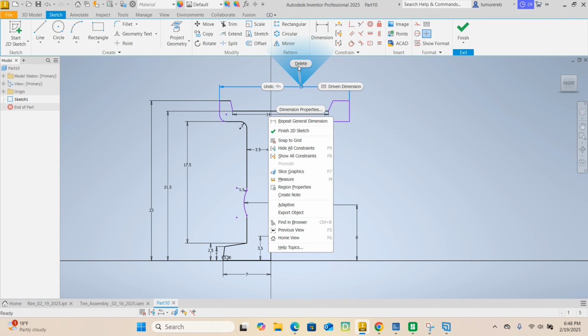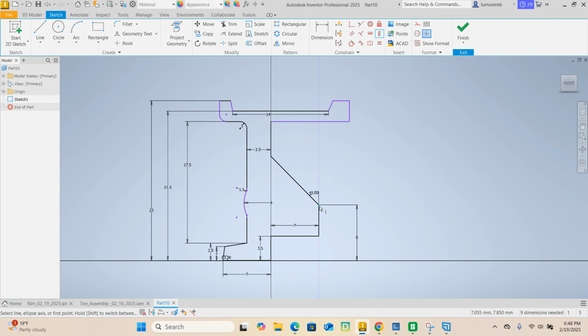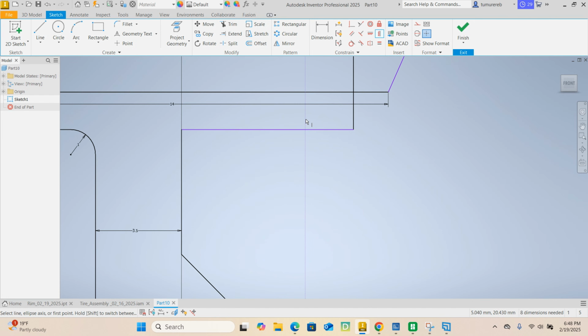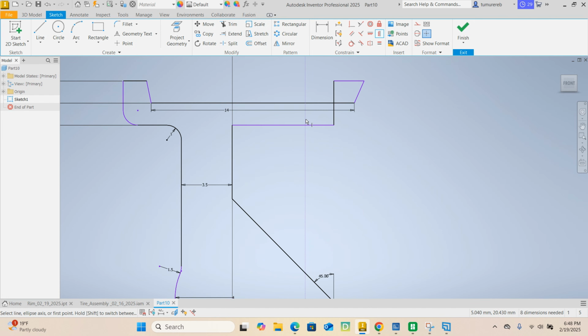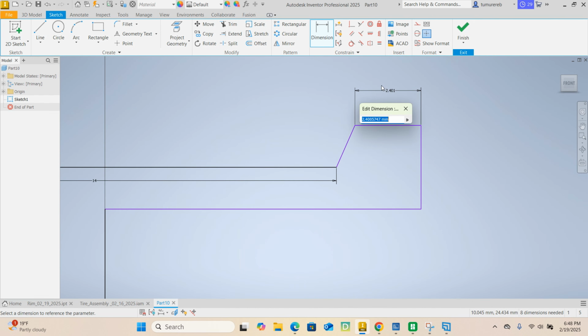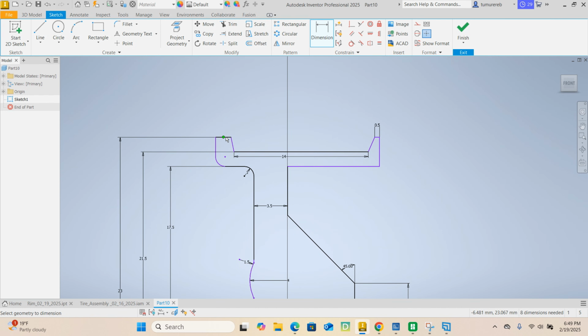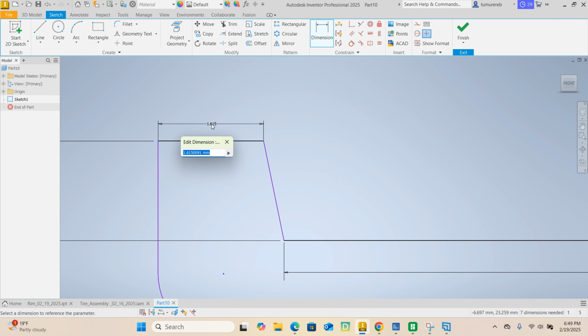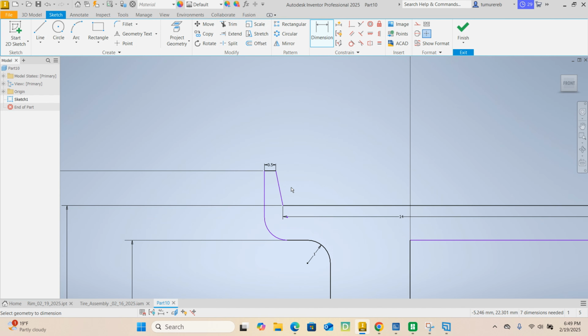How about, actually, let's go ahead and delete that. Use vertical constraints like that and that point there. No, no. Okay, undo that. I don't want to do that. Let me fix this. This distance here is going to be too big. 0.5. Same here, 0.5. Okay.